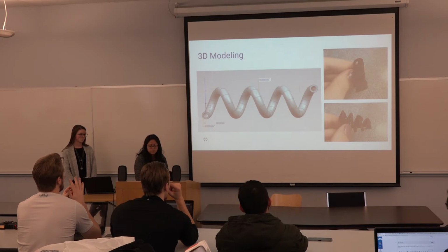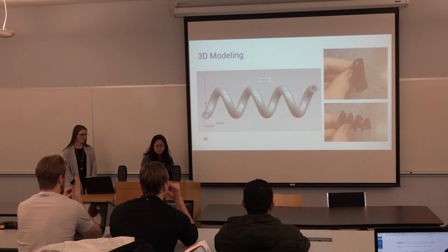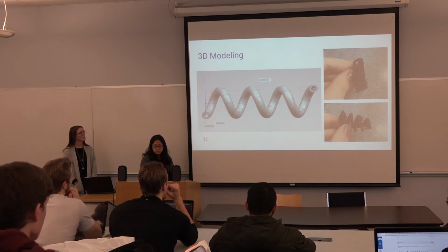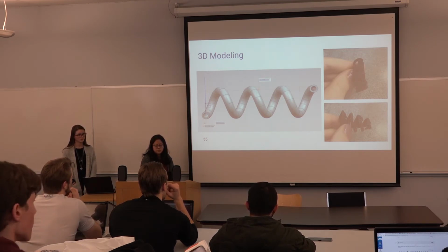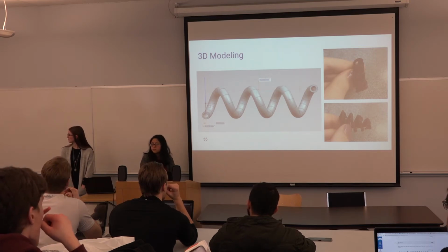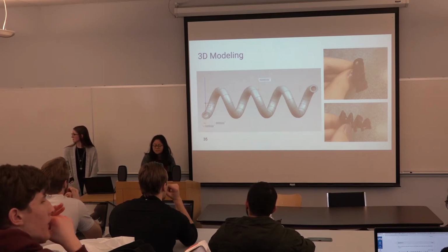It's hard to achieve a hollow tube with a 1.75 millimeter opening because it's too small for air to properly dry the inside of the cuff during fabrication. As a result, the inside of the cuff is still wet while the outside is dry. This wet interior really prevents the walls from completely solidifying, and this eventually will cause structural instability.